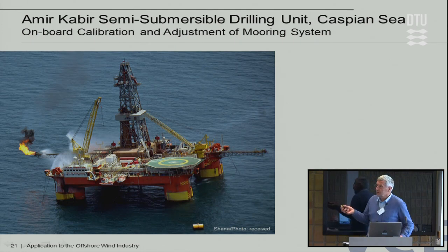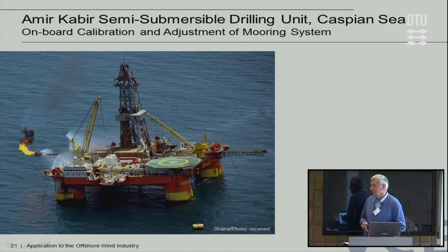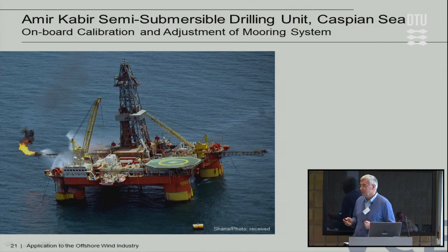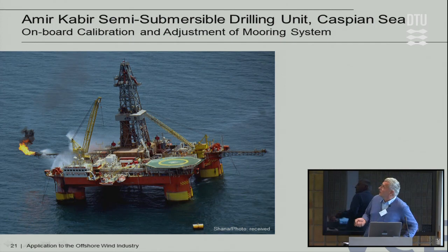But these things are standing on their piles. This is not a generator, it is a platform. And they are supported from the top, and they are swinging on the piles without checking. The jacket does not help. So it is a very difficult, complicated process to repair. And you will read it in the newspapers 2 years from now, I guess. This was an interesting case which we could eventually use.